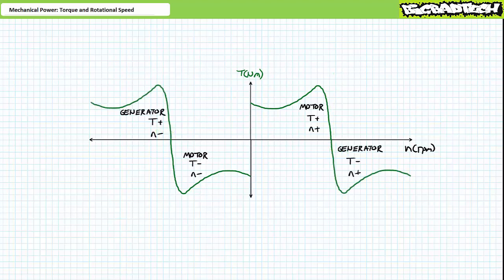The more comprehensive speed-torque curve now features two almost mirror images of the motor modes reflected through the horizontal axis. What does the extension on the right imply? Clockwise or positive speed, and counterclockwise or negative torque. Similarly, what does the extension on the left imply? Counterclockwise or negative speed, and clockwise or positive torque. Both of these regions of operation imply generator operation. Positive times negative equals the production of negative mechanical power, as does negative times positive.